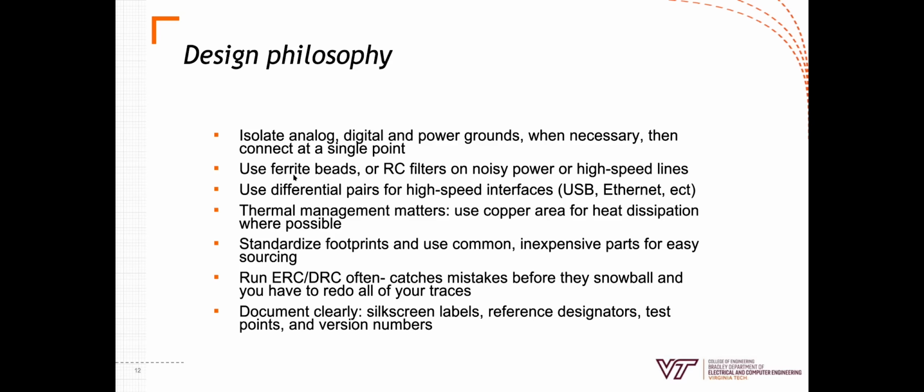Ferrite beads. Ferrite beads are really important for high-speed signal lines. It works as a high-pass filter, or not a high-pass, a low-pass filter, and it gets rid of any noise on that signal line that might interfere and give you corrupted data.